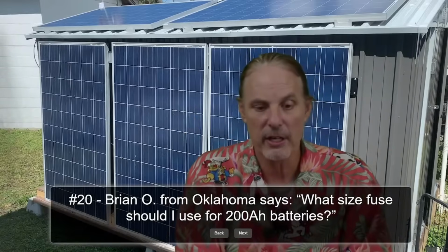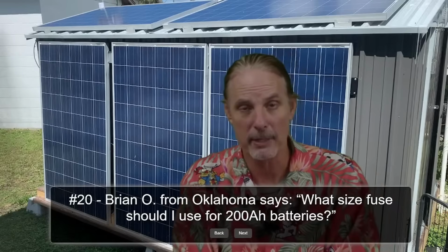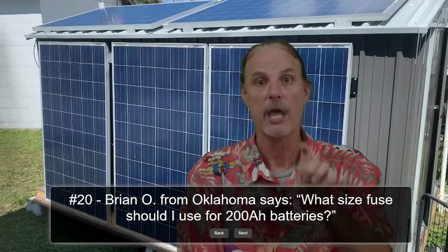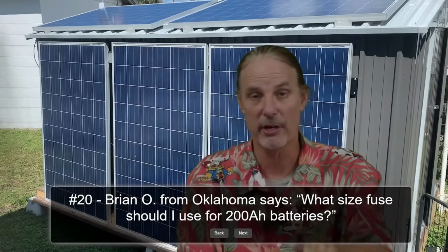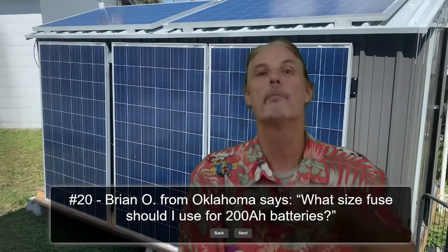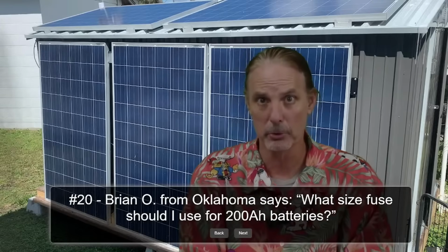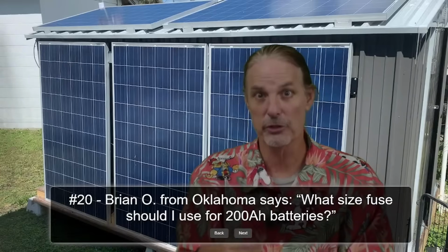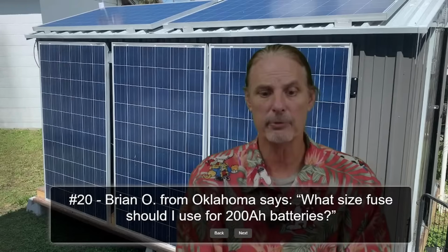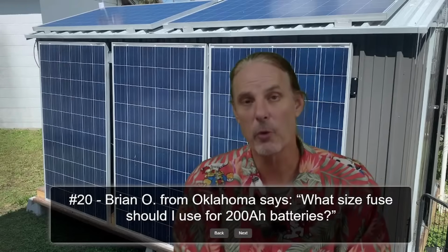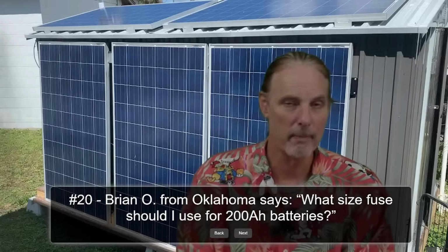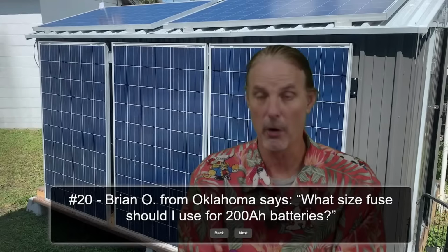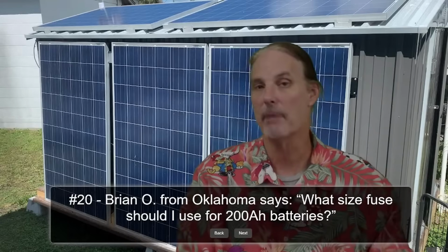So I would say that on a 200 amp hour battery with a 200 amp BMS, or any 200 amp BMS, you want to allow for a 20% variance. In other words, you want the fuse to pop when it goes 20% over the maximum pull. This will allow for spikes of turning on and quick surges and stuff like that. So 200 amps and a 20% variance would be a 240 amp fuse. They probably don't make a lot of 240 amp fuses, so you go with a 250 amp fuse is where I would go, which is exactly what I have in my RV.